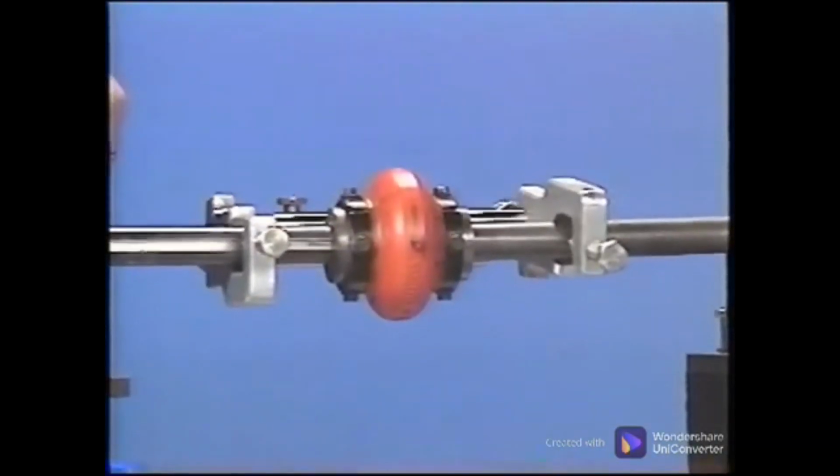To check that the measurements are valid, a rule of thumb can be used that the 2 side readings should total to the bottom reading. If the bottom reading is minus 15 mils, the side readings could be any numbers that will sum to that, such as minus 8 and minus 7, or minus 17 and plus 2.